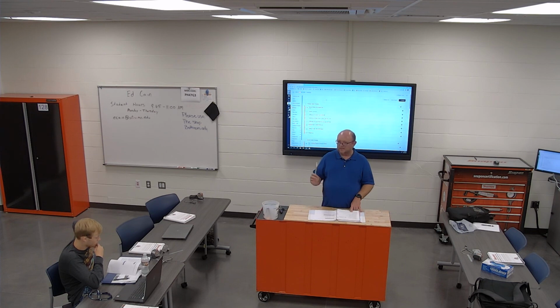Calculate drill point. It's the diameter of the drill times 0.3. If you want to just do the whole thing at once, I usually just do 1.3. That way it puts the tip and the rest together. It's just the way my brain works. But really, it's probably less confusing if you just do the times 0.3. So if we're doing a 1/2 inch hole and you want a blind hole and it's in a 1 inch block and it's going down 1/2 inch and you need full diameter to 1/2 inch, you take 0.5 times 0.3 and then add that to your depth. It'd be 650 thou. Make sense?